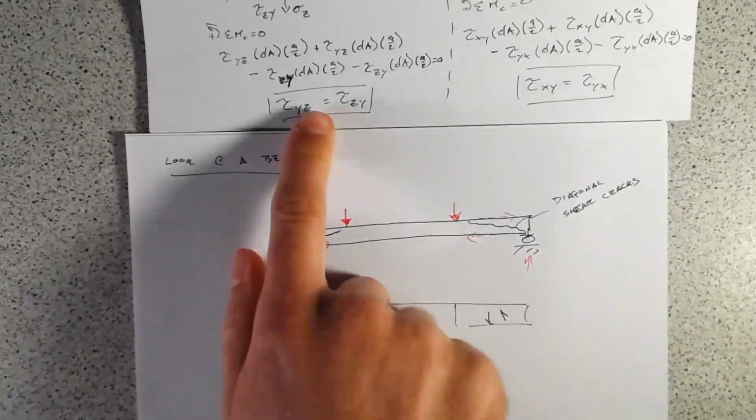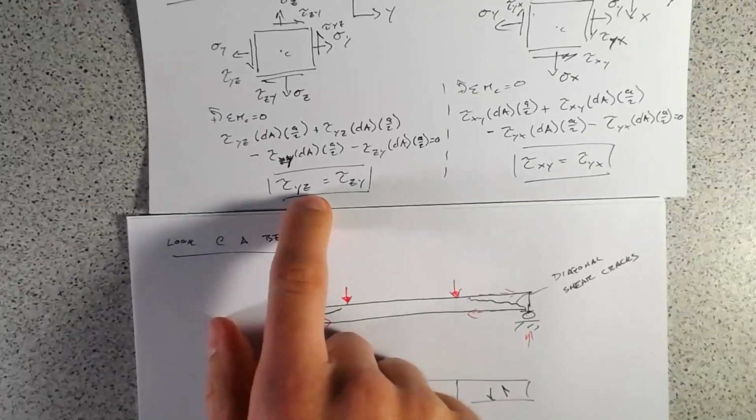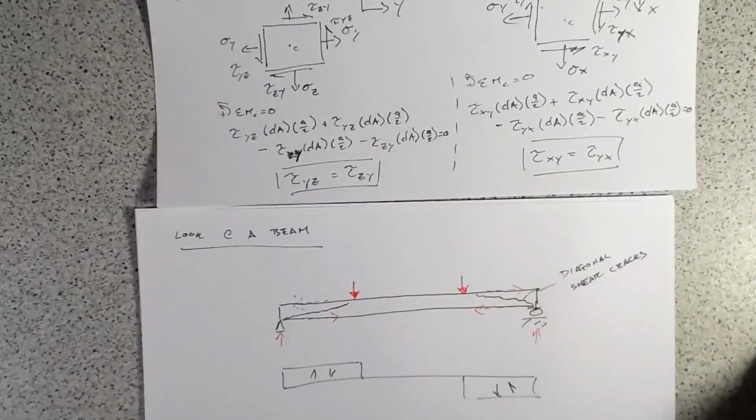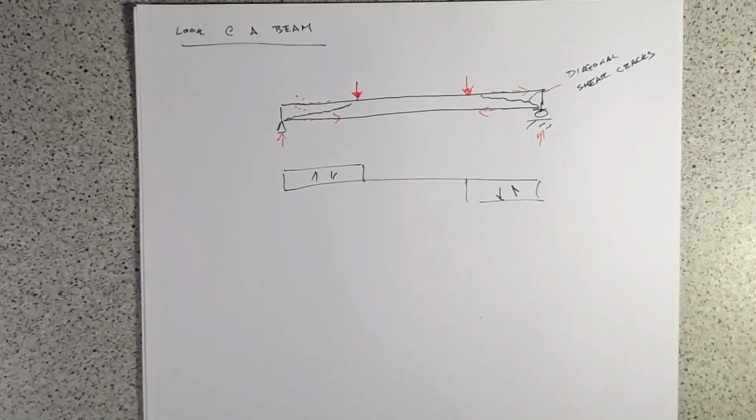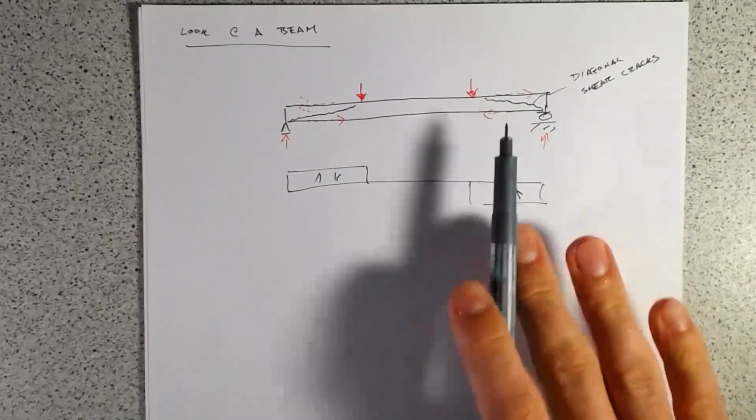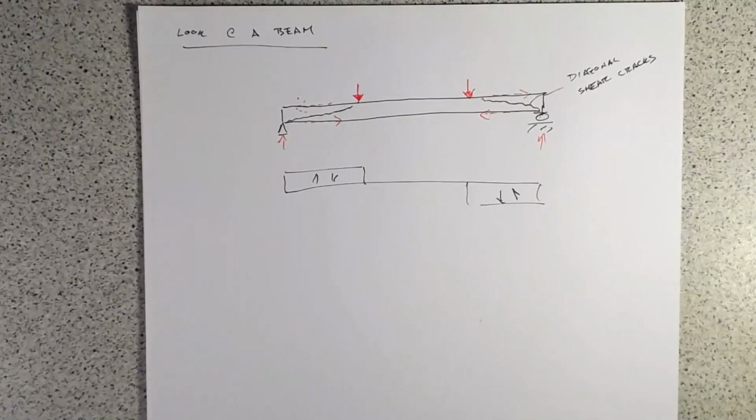And this all falls out of this rationale that if you have a transverse shear stress, you have to have a longitudinal shear stress, and that's going to become important as we go on in these next few lectures, where what we want to look at is the distribution of these stresses as we go across a given member or over a given section. And that little nugget of truth is going to help us derive those sections.